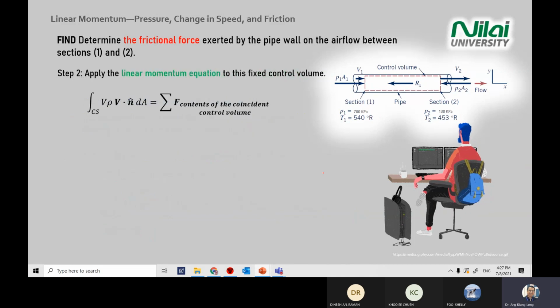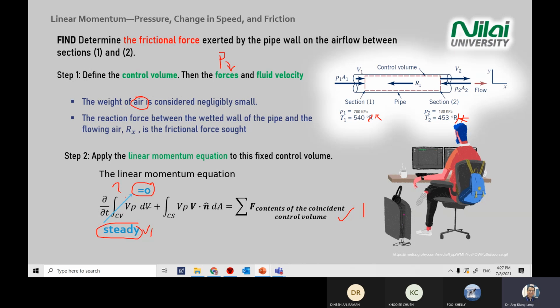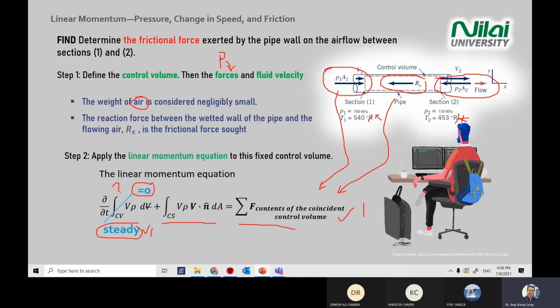Next, look at the screen. Pull the equation up. Because the control volume side already cancelled, you only need to solve for the control surfaces component and the force. The forces you just read from your free body diagram. With all the force here, you know from the free body diagram that you have 3 forces on the right hand side. You just pull them to the right hand side and compare to the axis that you have.